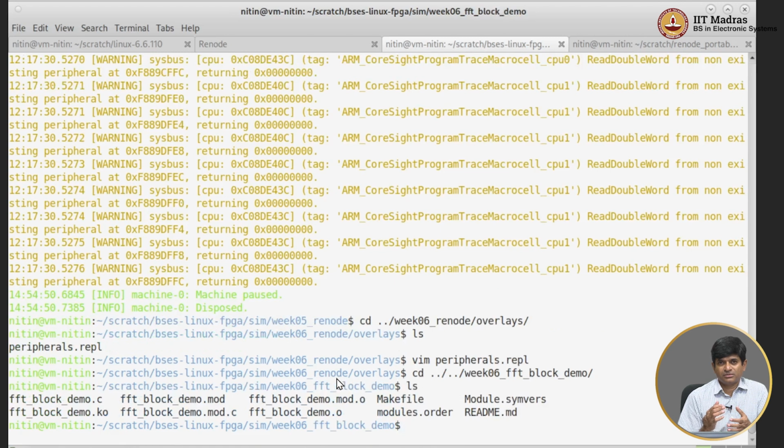We looked at how the smart timer module works, but that's pretty much a repeat of what was done earlier. The only thing that we have done differently over here is we understood a little bit more about the kinds of APIs that are used and how we can go about creating a smart timer driver, which can be automatically mod probed by looking for the compatibility flags.